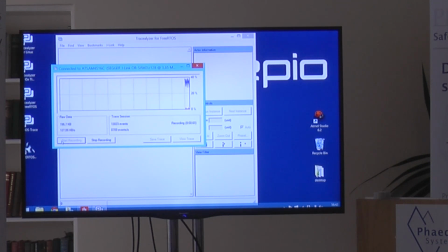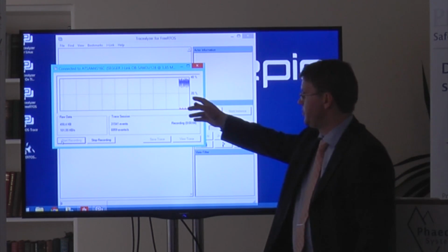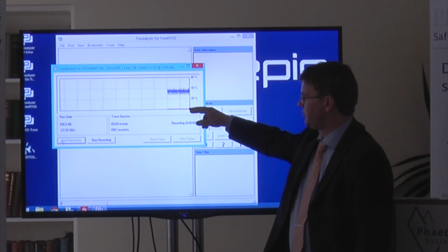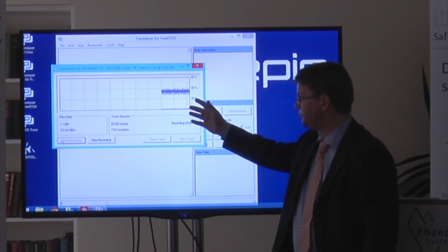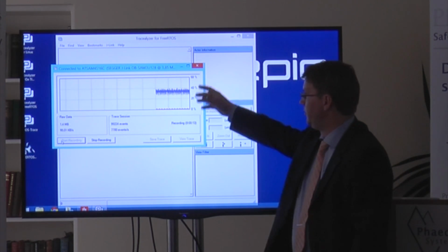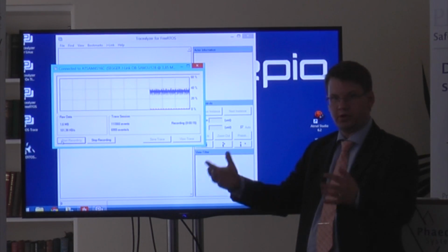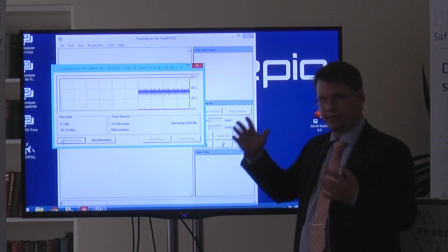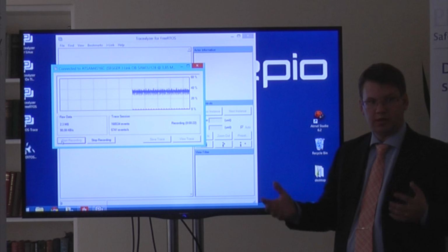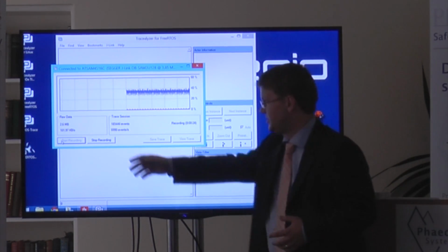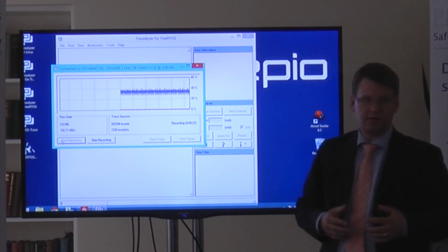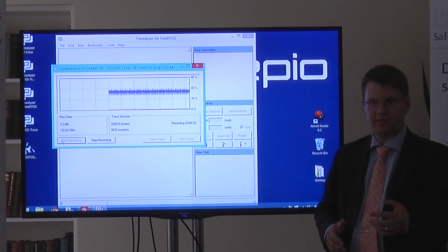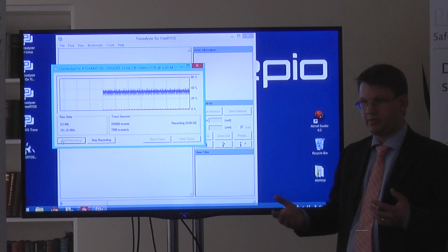And now we get a view like this, a live view showing the CPU usage of all the application tasks and any instrumented interrupts in the application. This is mainly to get a sense of what's going on in real time. And then when you stop this, you get a file that you can store and visualize. And here you see the amount of data we record. It's about 100 kilobytes per second at the moment. That would translate into a few hundred megabytes an hour. So it's quite a manageable amount of data.